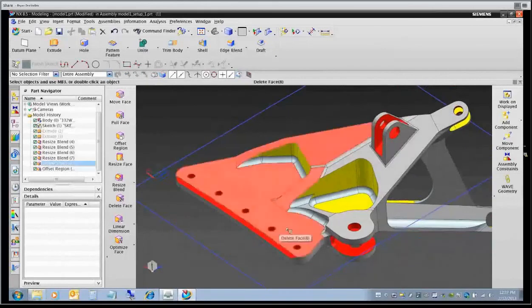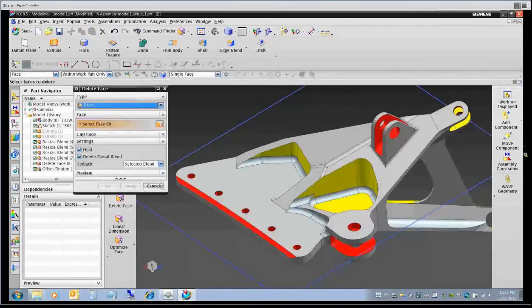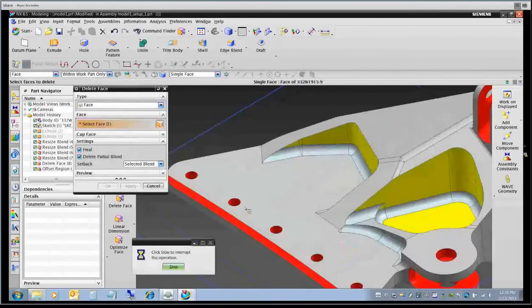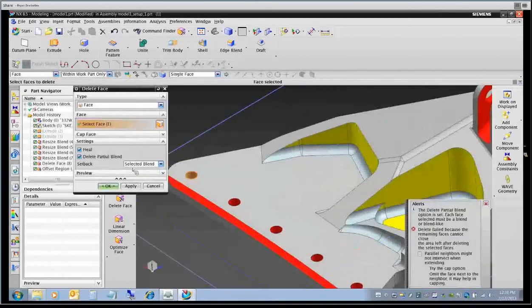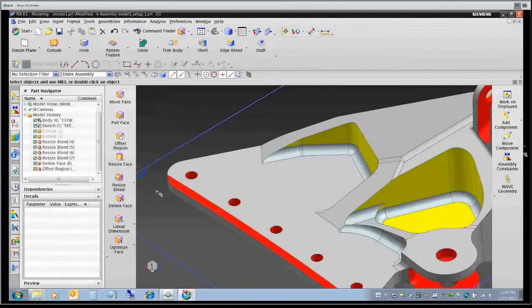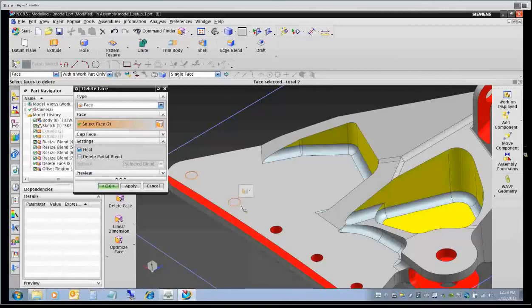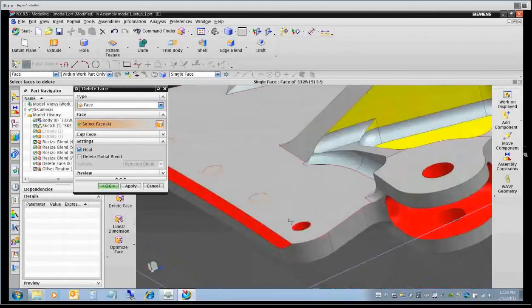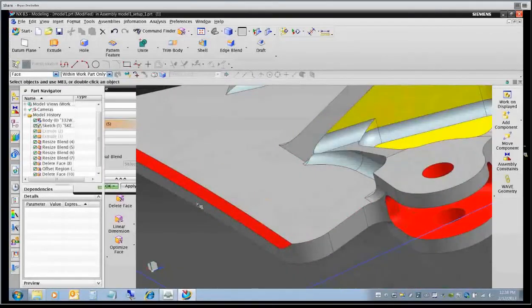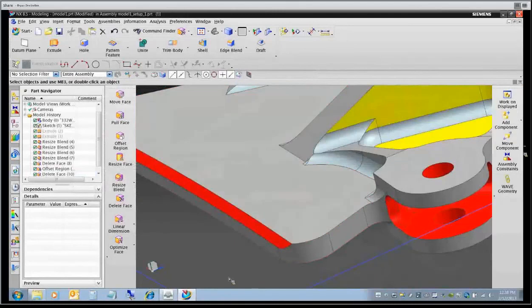Like the holes, for instance, if we wanted to make this as the casting stock for this part rather than do it from a billet, we would go into the part and literally select these areas here, and go back and remove particular part areas. So if you wanted to, we just delete these, and it refeatures the part basically back into a solid, just like these features. And they're not patches on the hole. It actually is completely healed, so you don't have the surface scarring going on.